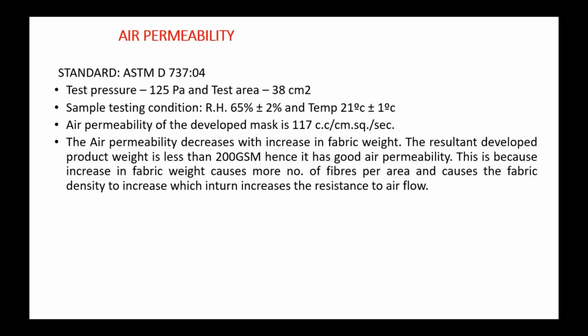I carried out the test. The test pressure imparted in the machine is 125 Pascal, and the test area of the sample is 38 by 38 centimeters. The atmospheric air condition has been maintained: 65 plus or minus 2% RH and 21 plus or minus 1 degree Celsius. My developed mask arrived at 117 cubic centimeters per second per square centimeter as the air permeability value.